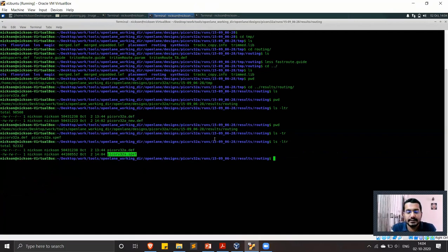So in our post route STA analysis, the only thing different from what we did earlier was, first you have to create a new DB, because the def has changed, and the DB should have the def obtained after routing as the def. Second thing is, you need to use the Verilog file which was created pre-routing.